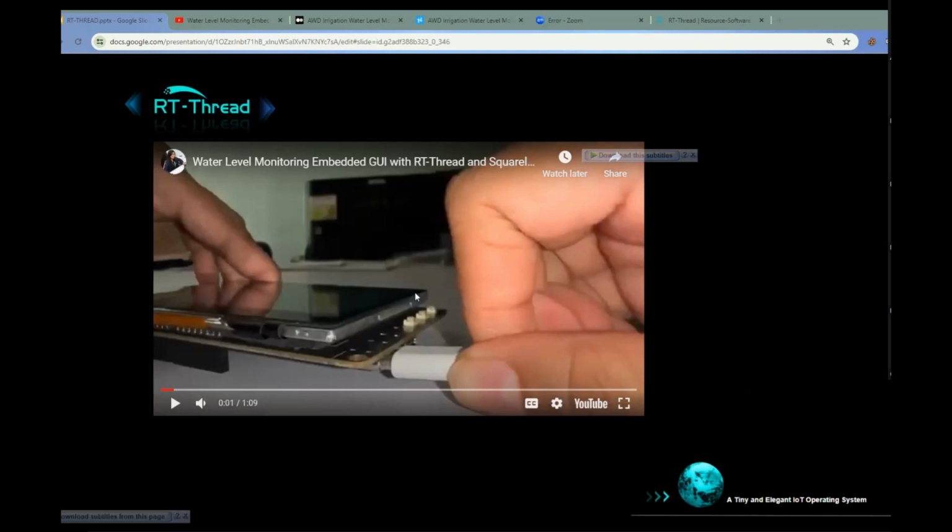In your HMI display, it's particular using specific software. We can design your GUI and then upload it into the board. So I think the similar thing we can compare to is the Arduino. It's just that the Arduino is for controlling and the HMI is for interfaces. But actually, we can integrate them because the HMI board can be integrated with microcontrollers.